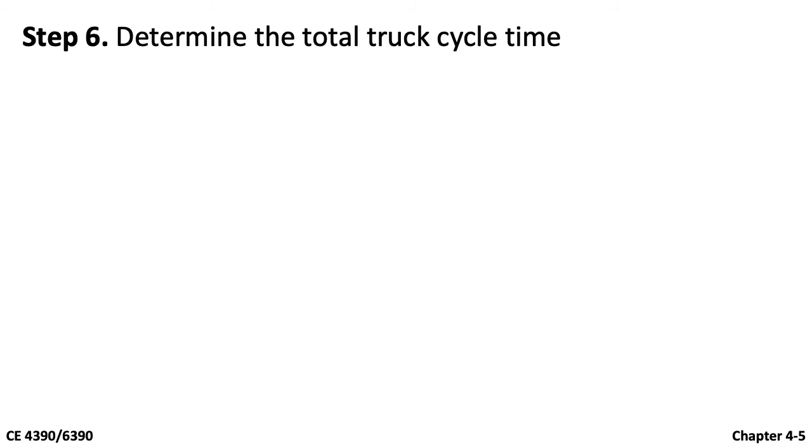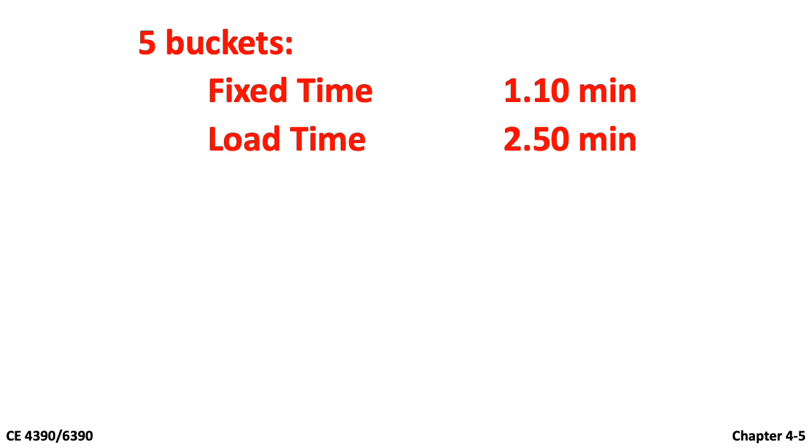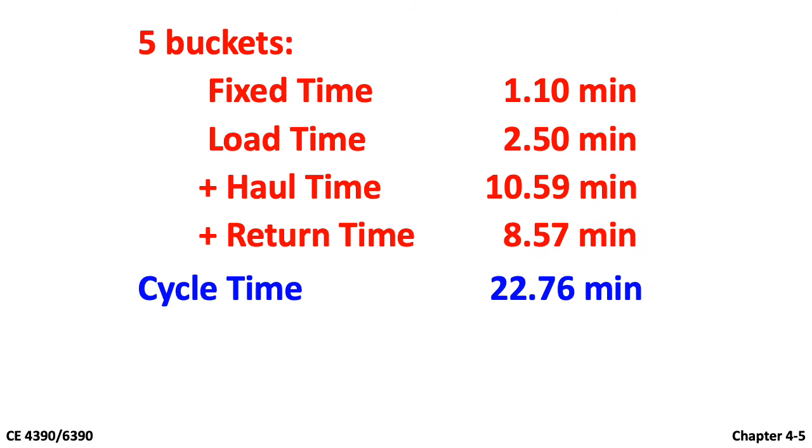Step number 6, determine the total truck cycle time. By adding all the time components, fixed, load, haul, return, you get the total cycle time. With 4 buckets, it is 21.67 minutes. With 5 buckets, you got 22.76 minutes.